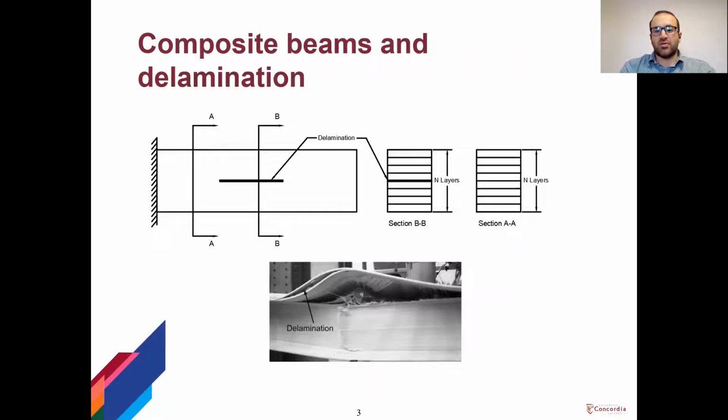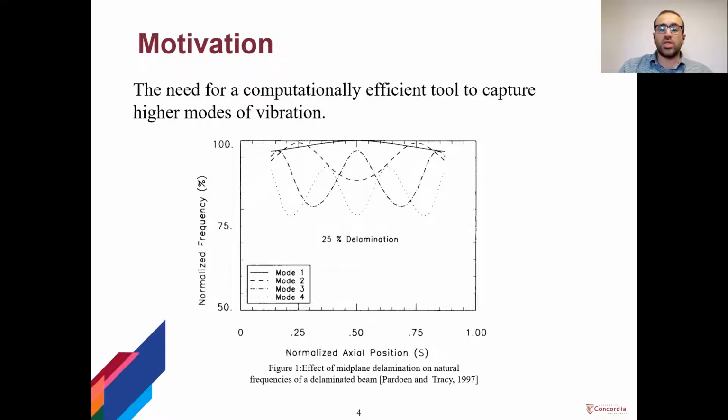Composite structures offer an advantage for structures which require a combination of high strength and low weight. In contrast to their in-plane properties, transverse tensile and interlaminar shear strength of laminated composite beams are quite low. Consequently, laminated composite beams are prone to delamination from a wide variety of sources, such as fabrication stresses, environmental cycling, handling damages, etc. Delamination not only affects the strength and integrity of the structure by contributing to its final failure, but also causes a reduction in the stiffness, thus affecting its vibration characteristics. However, we can use this effect on vibration properties to detect the delamination.